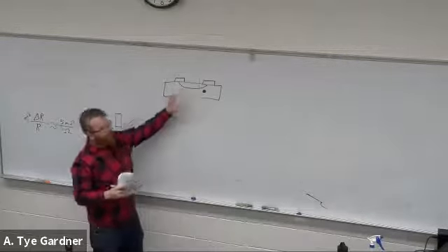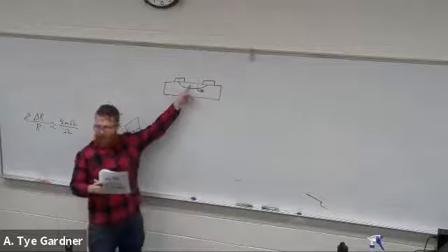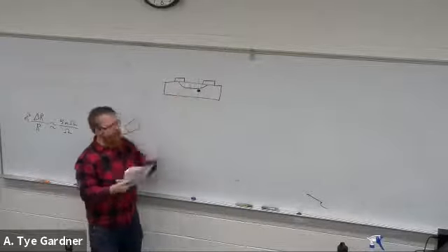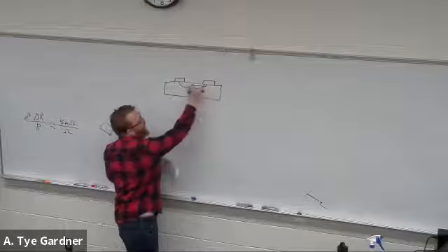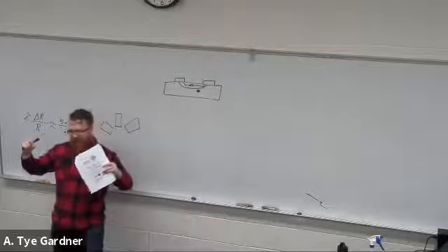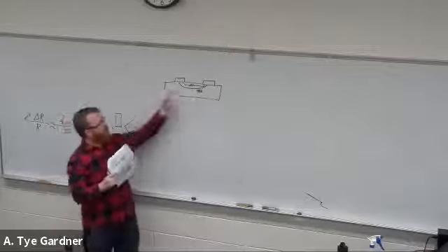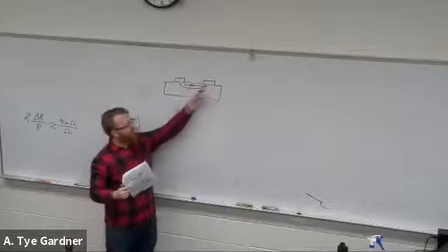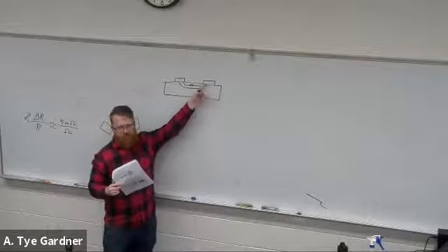So if I have a very basic model where this little pocket is my doped silicon, and I just have two simple contacts, there's going to be some resistance in here. And as it bends, it changes, as long as my voltage across does not change. So this is very sensitive to changes in voltage.